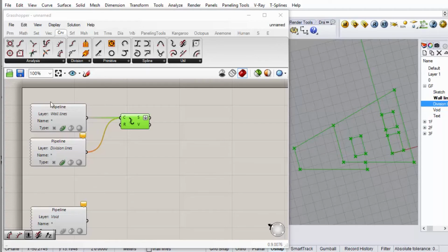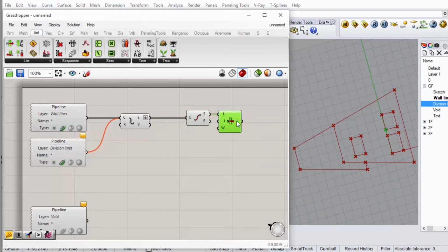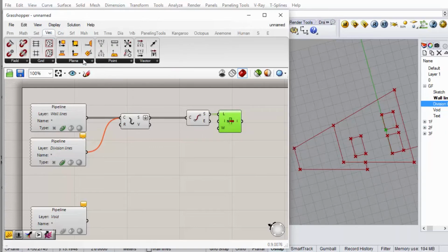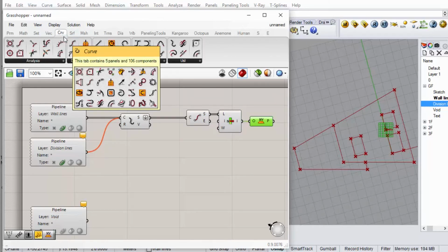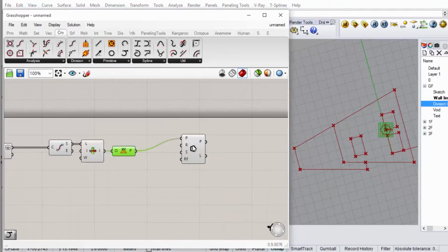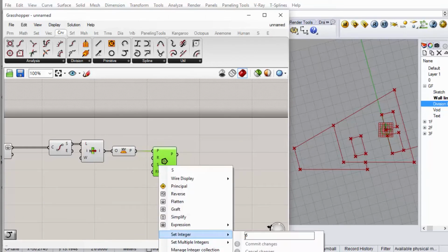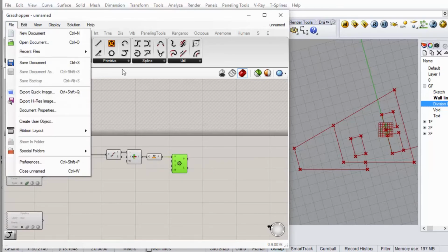So in order to do that, it's just easy to take any point that lies on here, just take the start points, and then just take any start point that you want, just as long as it's just one, because we only want one surface, and then use that to create a plane, which we're then going to use to create a large four-sided polygon. Number of segments, we want 4.